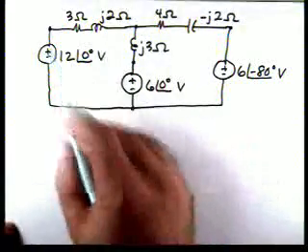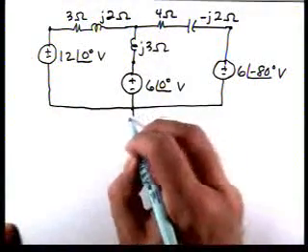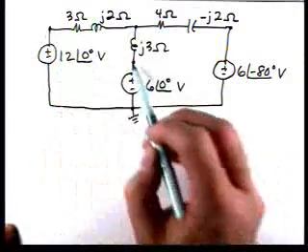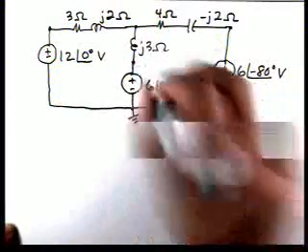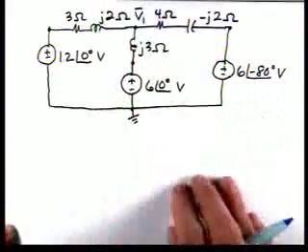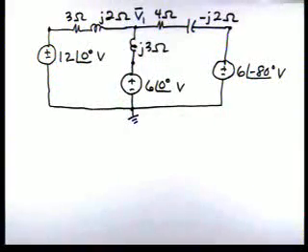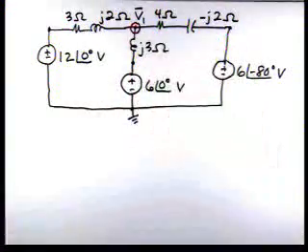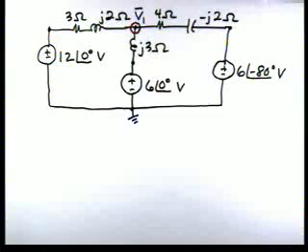Okay? 3 of the node voltages. So, for instance, if we pick this one as a reference, this node voltage is known, this node voltage is known, and there's only one unknown node voltage, and I'm going to call it V1. So let's write a nodal equation for that node to solve for V1. Then once we have V1, we can calculate the currents.